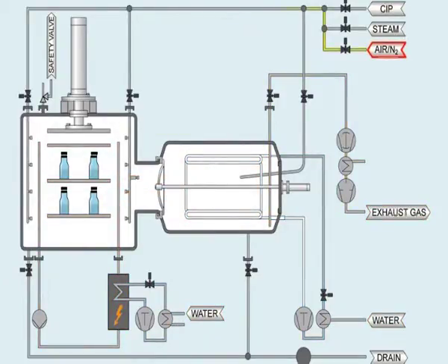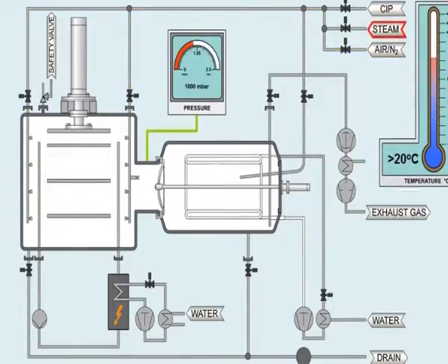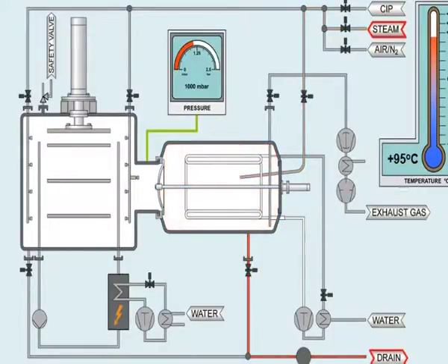Depending on the drug substance dissolved in the water, the eutectic point is determined. Their usual range is from -10 degrees centigrade to -30 degrees centigrade. A condition of 1 to 8 Kelvin below the eutectic point is sufficient. Vacuum is applied to the tune of about 3 mm Hg on the frozen sample, and the temperature is linearly increased by about 30 degrees centigrade in a span of 2 hours.